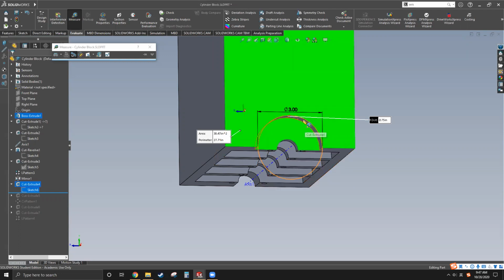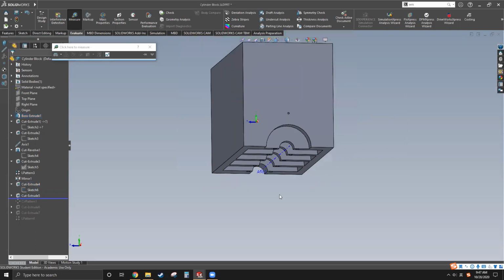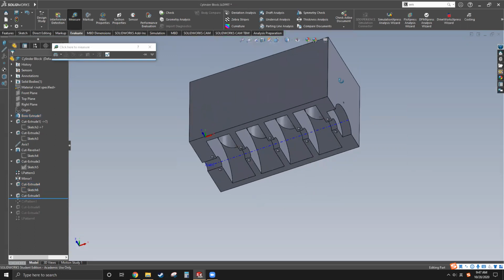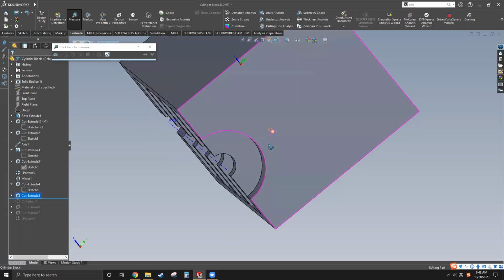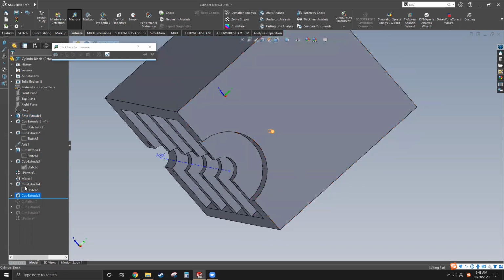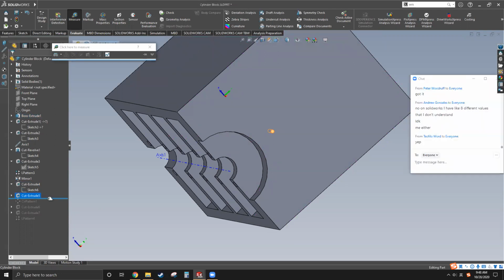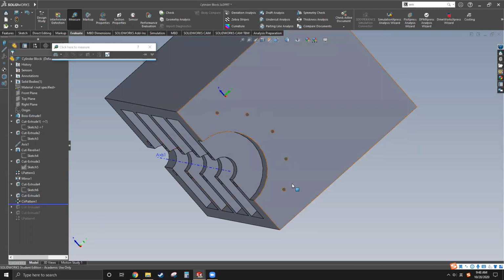So is this okay? All right, another one is another set of cut extrude. So this one is a small hole on top. Let's ignore this because this hole doesn't do anything to this assembly. It is one of the details that's supposed to be on the engine. You will see the circular pattern is associated with this, but it's not going to do anything to this assembly. So let's omit it.